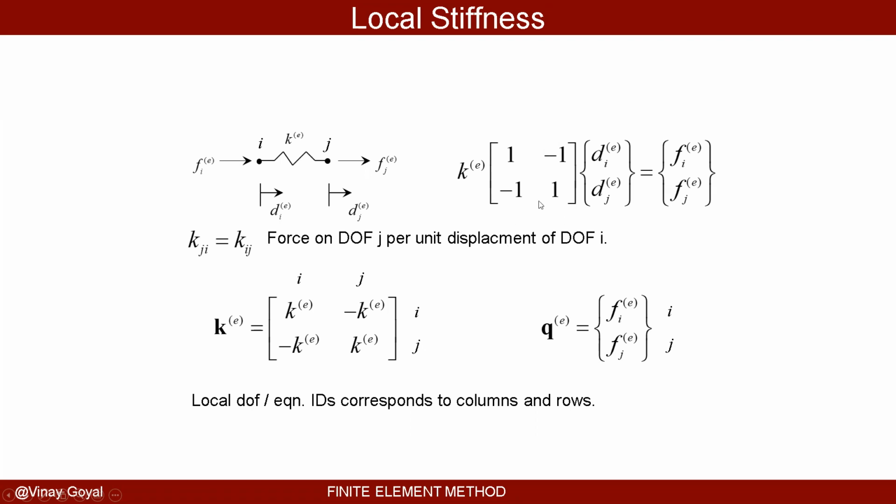So it works out very nicely that the force becomes a spring constant when you apply a unit deflection. But the bottom line that we wanted to make here, not to confuse anybody, is that the stiffness matrices tend to be symmetric because of that for linear systems.